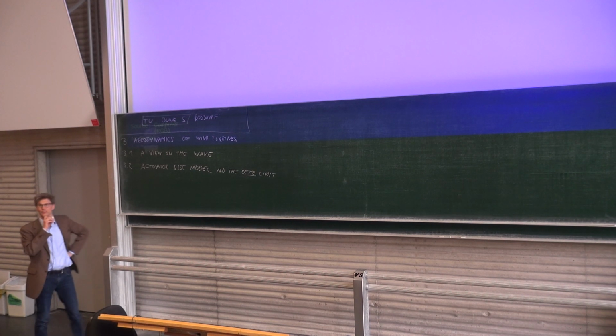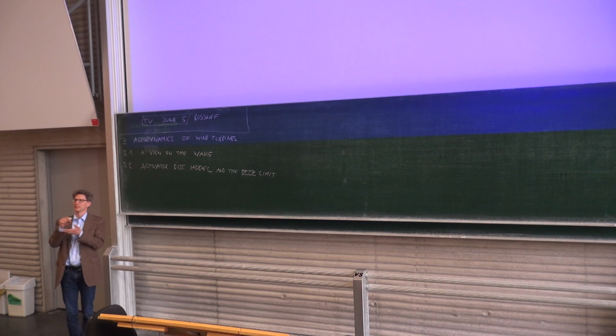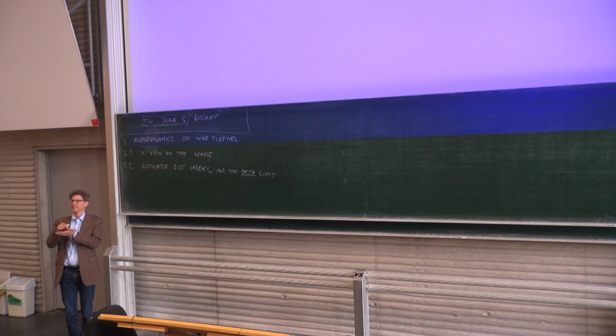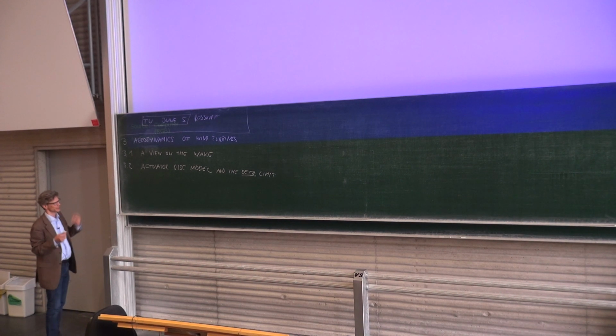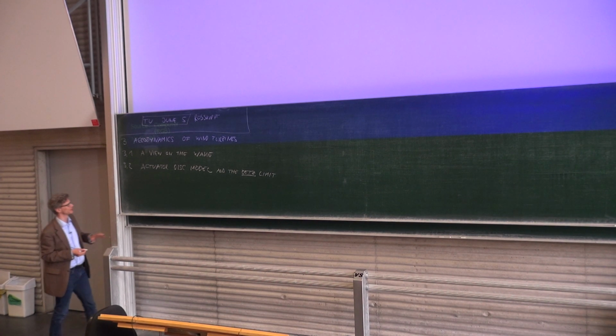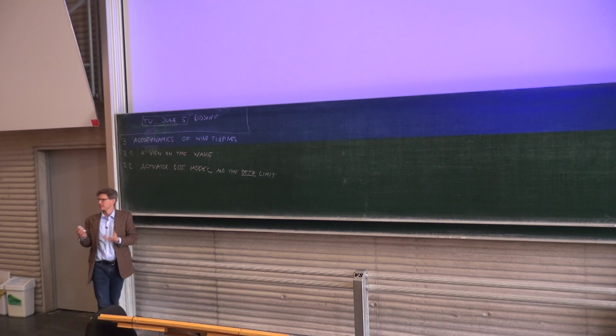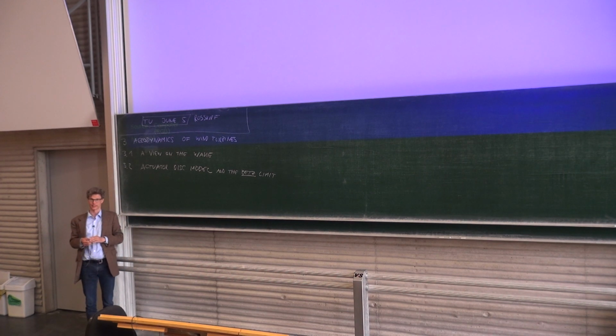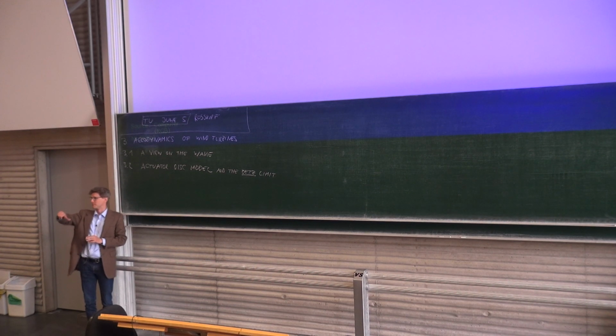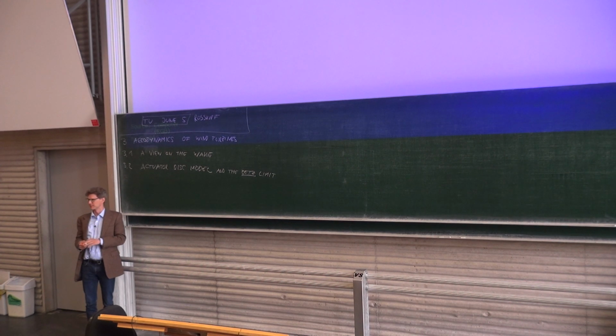And he was writing one of the first textbooks on wind energy, which I also have. It's a very thin one. And if you are able to read old German typewriting, which is Fraktur, it's not very easy to read, but then you will enjoy this little book. So in this book, he derived what we now call actuator disk model and his limit. And this limit will actually tell us how much energy a wind turbine can extract from a given wind flow, and it's significantly lower than what we would get from our first estimate. As Rachel said, it's around 60%.